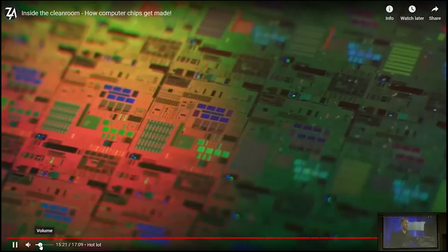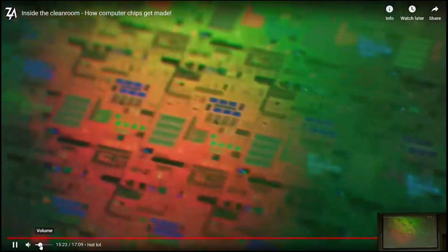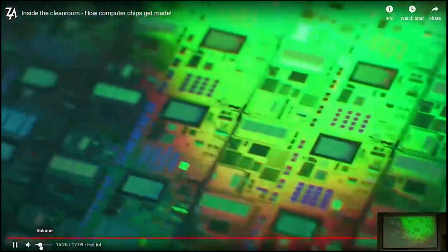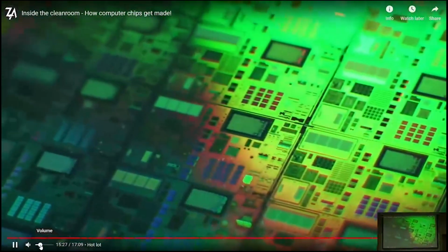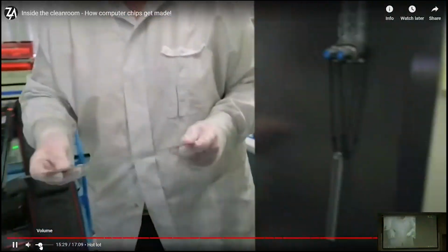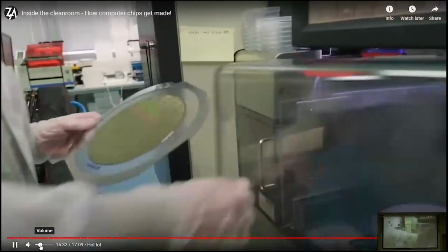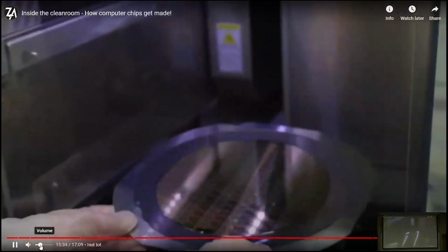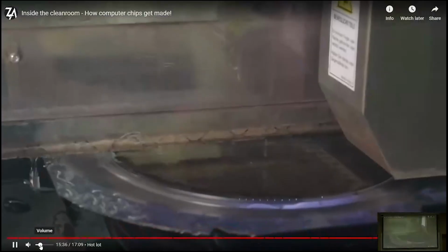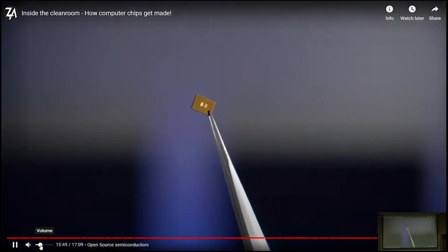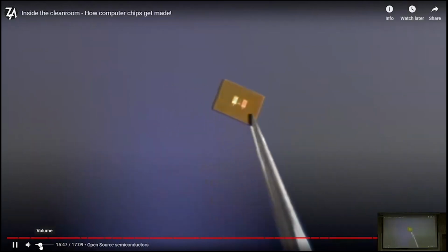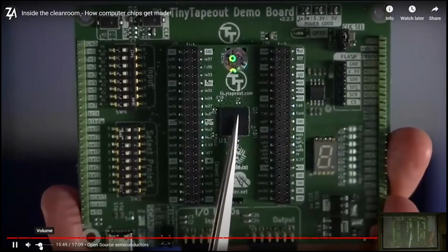To build a whole wafer, it takes about 600 steps, and that takes 3 to 4 months to produce a whole wafer. Once we build up all the layers, the final step is a passivation out of silicon dioxide and silicon nitride, but there we still have to etch some holes to connect our integrated circuit. After all these process steps and all this waiting, the wafer finally comes out of the cleanroom and is diced into little pieces and ready for use. After the wafer is diced into individual chips, they're normally encased in a plastic package, making them easier to handle.